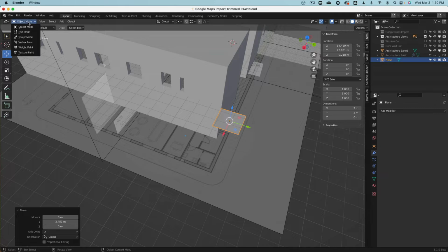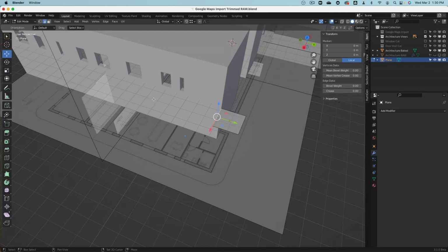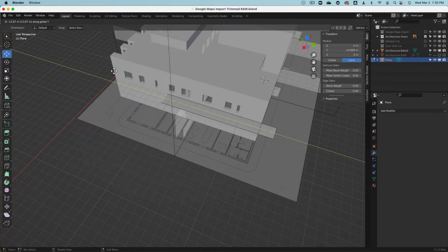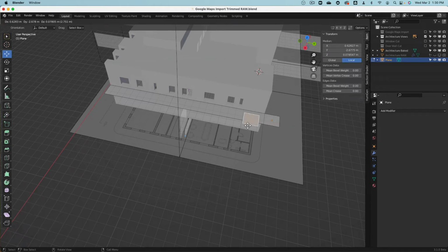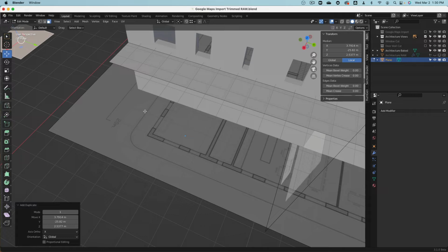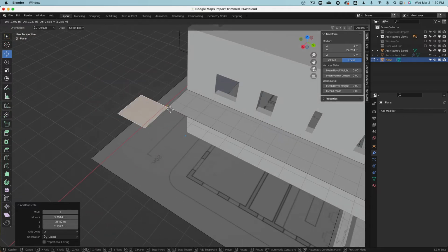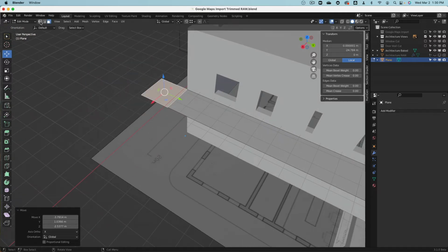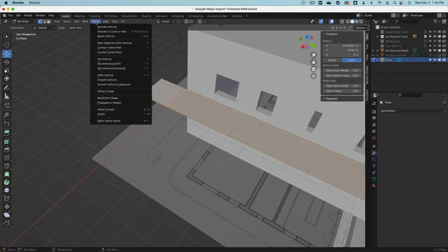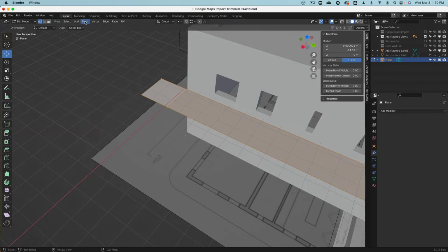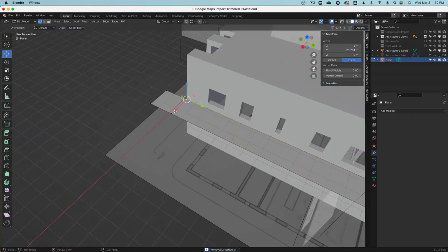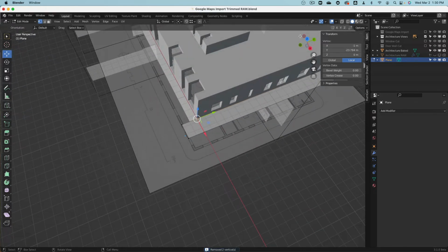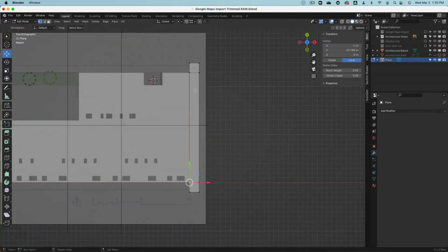Go into edit mode. I select this face, E and Y. Go to there, hold control, there we are. Go to face, select this face. Shift D, move this to here. Then G, hold control to there. A, select everything, and then we clean everything up. Again, this got fused together. So this way, as you can see, we actually quickly built this walkway.